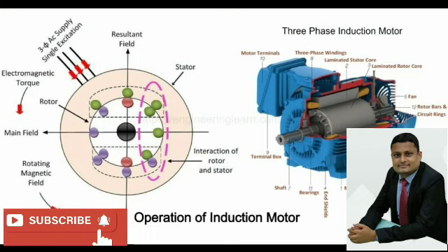Now we will discuss the design of a stator. We will go very fast, so please keep noting. We have 0.35 to 0.5 mm thickness steel lamination, HRS or CRNGO, not CRGO. If the length is more than that, cooling ducts should be provided every 10 centimeters.